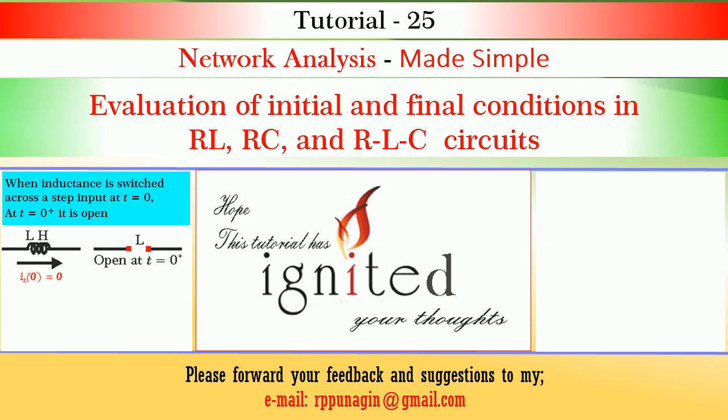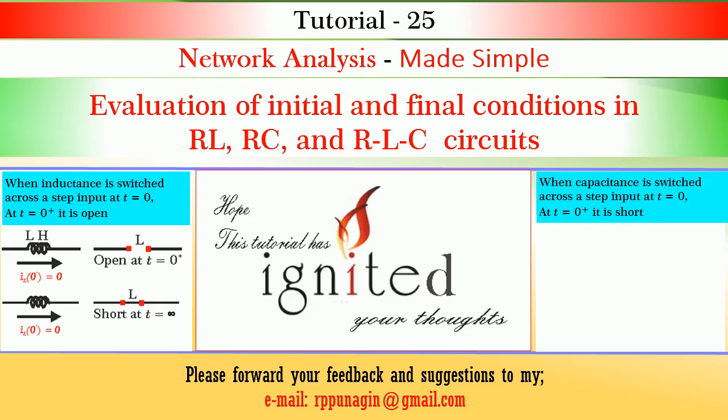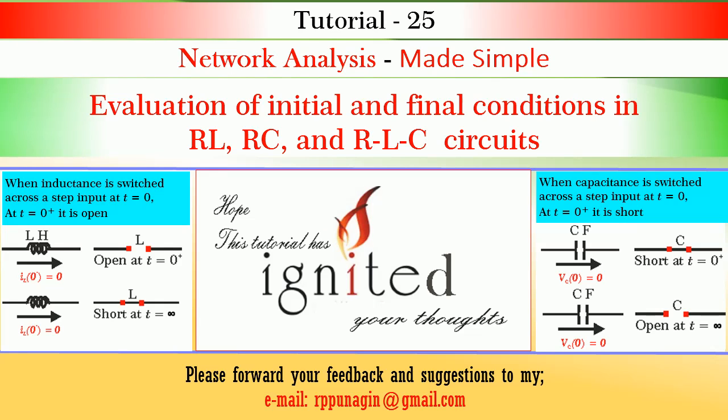That's all. If you remember only this, you can extrapolate that at t is equal to infinity, L is short, at t is equal to 0 plus, C is short, and at t is equal to infinity, C is open. It is the reverse of inductance. Also, if there is initial current through the inductance and initial voltage across the capacitance, inductance will act as a current source and capacitance will act as a voltage source, both at t is equal to 0 plus and at t is equal to infinity.